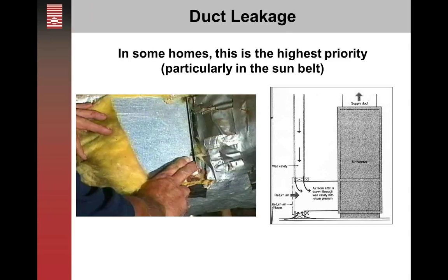The drawing on the right-hand side also gives you an idea that if we don't seal all the wall cavities, and they may be connected to various systems like an air handler or the return airflow, that is going to cause a leak that affects energy efficiency, comfort of the house, and how the occupants are enjoying their facility.